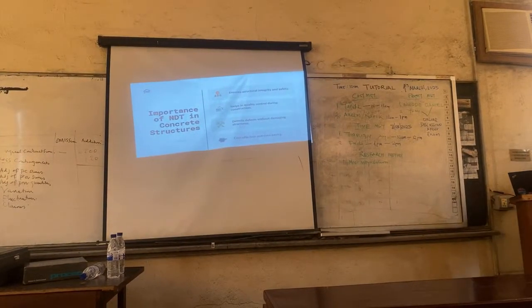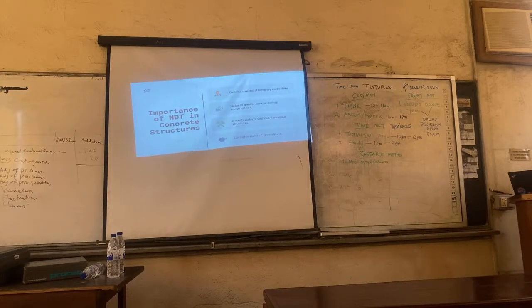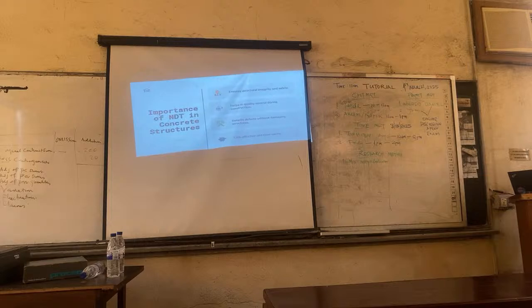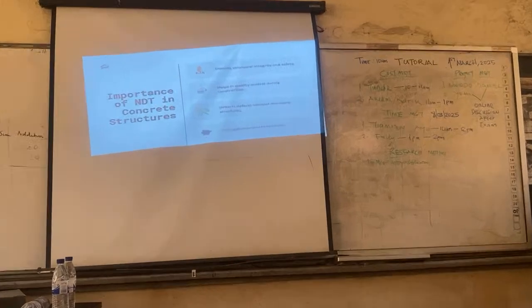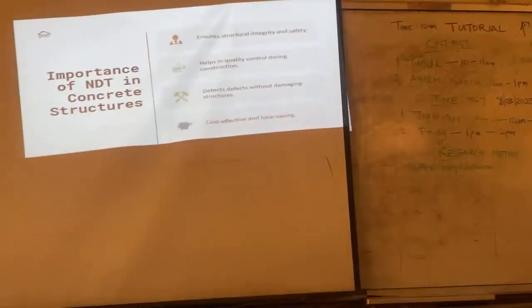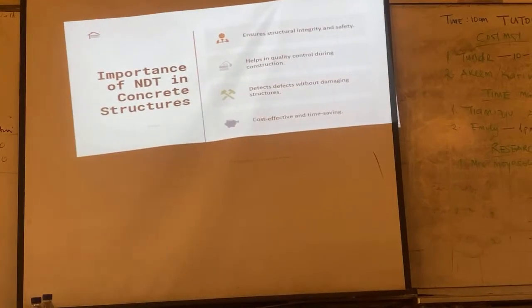We know about crushing cubes to check for compressive strength. When you are casting slabs and columns, you get specimens, you cure them in curing tanks, you crush them to know the compressive strength, and then the state can tell you, okay, yes, this building is good enough to be used for whatever purpose it's being created for. But with NDT, you don't need to create specimens. You just need to carry out a test, and that's what we are talking about today.